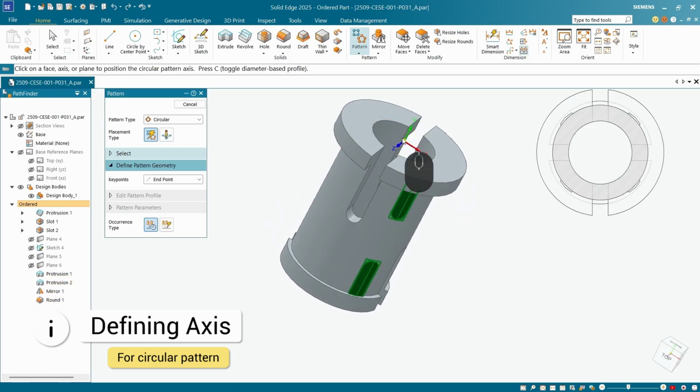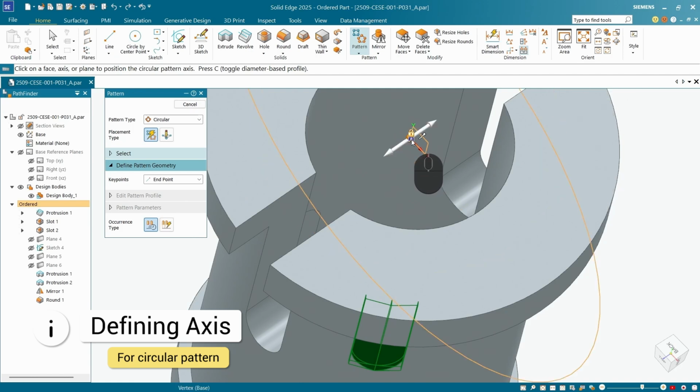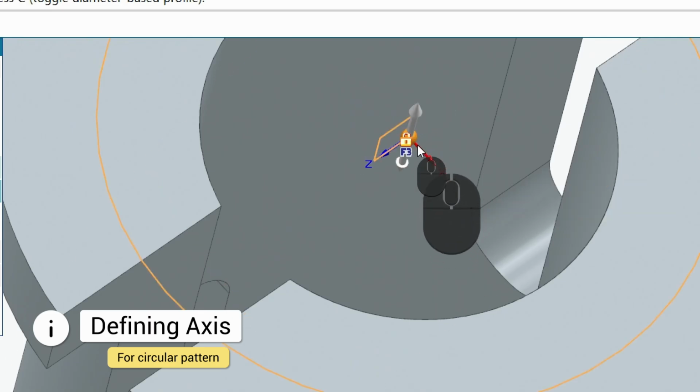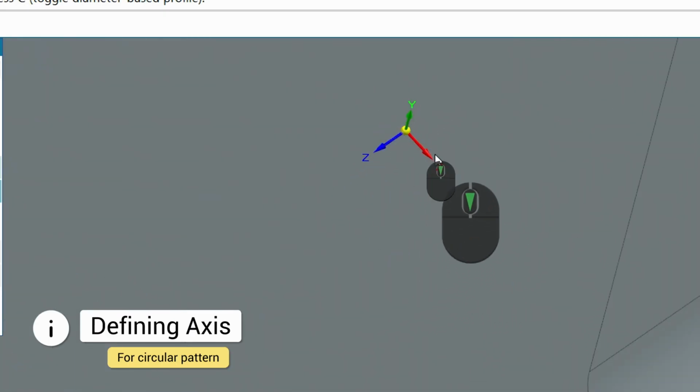Let's maybe have a look, see if we can. I'm just moving around. This looks close to what we want. So I'm selecting the, you can see, very difficult to see. So let me just zoom in. So you can see we have our base coordinate system. And as I move around, even just a tiny move can change things. We don't want it on our x-axis. We don't want it on our z-axis. We want our y-axis. So there it's moving along our y-axis.